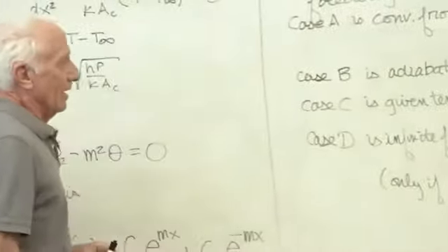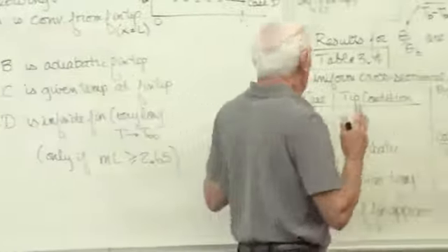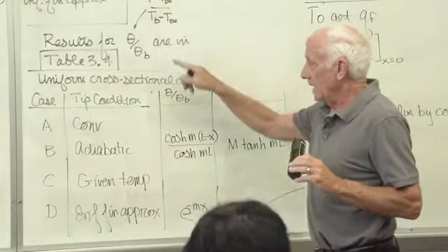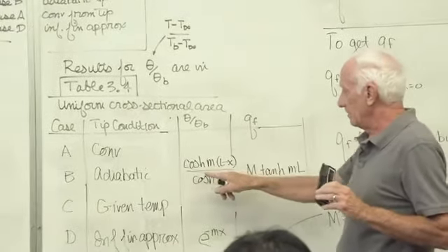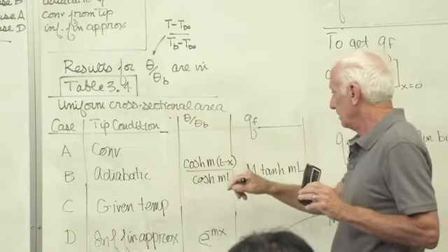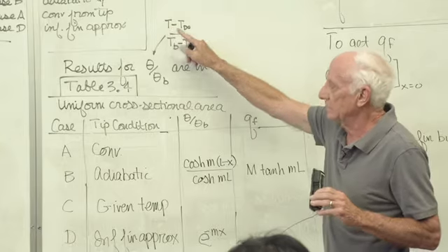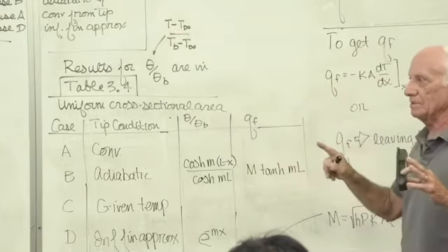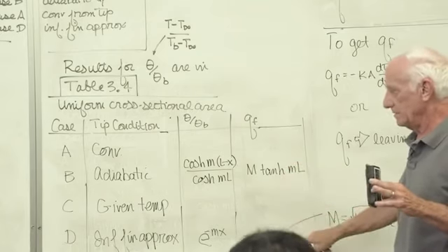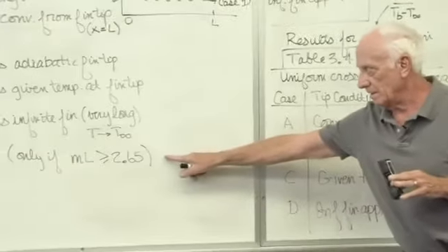Now, what have we got so far? In that picture over there, you give me an x and I'll tell you the temperature. There it is. x equals 5 centimeters, L is 10 centimeters. Got it. Put it in here. Solve for T, the temperature at that location. Second thing, how much heat is lost by that fin? There it is for an adiabatic fin tip. There it is for a very, very long fin. That's what very, very long means right there.